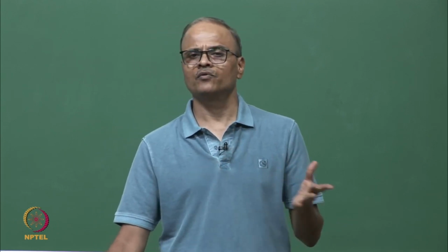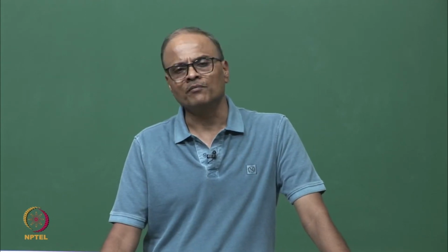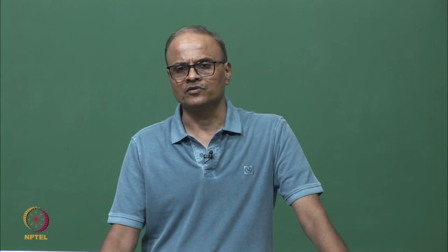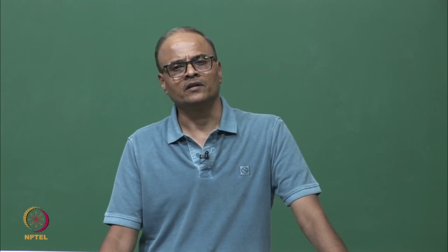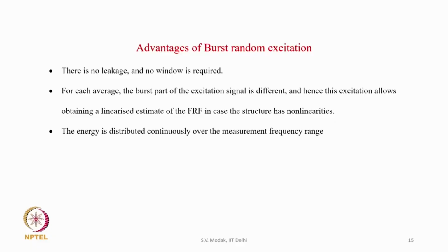So, a broad range of force amplitude gets used to excite the structure, which results in a broad range of amplitudes of the response, and any nonlinear response, if generated, gets averaged out, resulting in a linearized estimate of the FRF. Another advantage is that the energy is distributed continuously over the measurement frequency range, unlike the pseudo and periodic random excitations, which have energy concentrated at discrete frequencies.